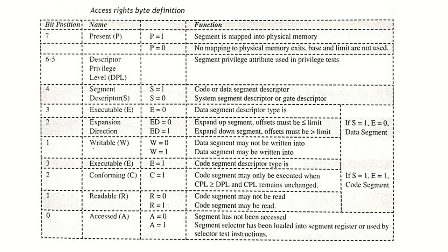That means looking at your privilege level. When you are requesting a code segment or a data segment descriptor to be fetched, what is your current privilege level, what is your requester privilege level, and what is the descriptor privilege level? The code is the current privilege level, whatever you are requesting is the requester privilege level, and the descriptor which you are fetching, whether code or data, has the descriptor privilege level.